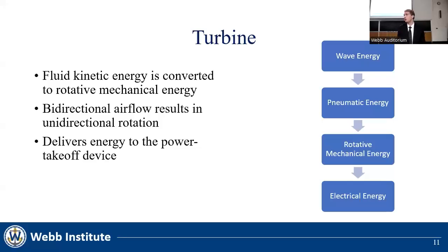As with any energy transfer process, there are inherent losses. So a major goal of this thesis is to maximize the efficiency of this energy transfer. A unique feature of this device is that the working fluid of the turbine is the air, not the water. Finally, due to the cyclic nature of the waves, the turbine must be able to handle bidirectional airflow and rectify